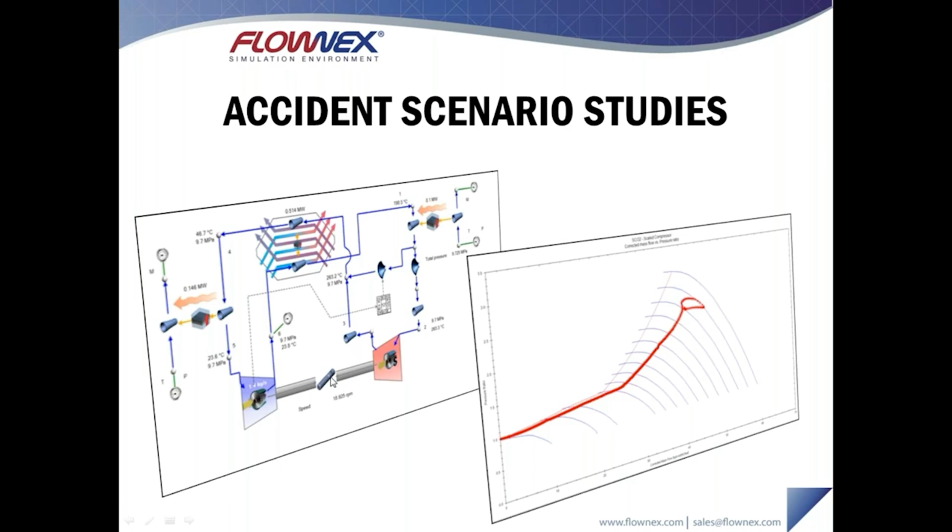This turbine is then coupled through a shaft to a compressor. The heat sink in the system is over here, a water line, and then we have a recuperator modeled over here. The two valves or restrictors that you see over here represent the turbine control valve as well as the bypass valve. In controlling these two valves, we can actually shut the system down safely.